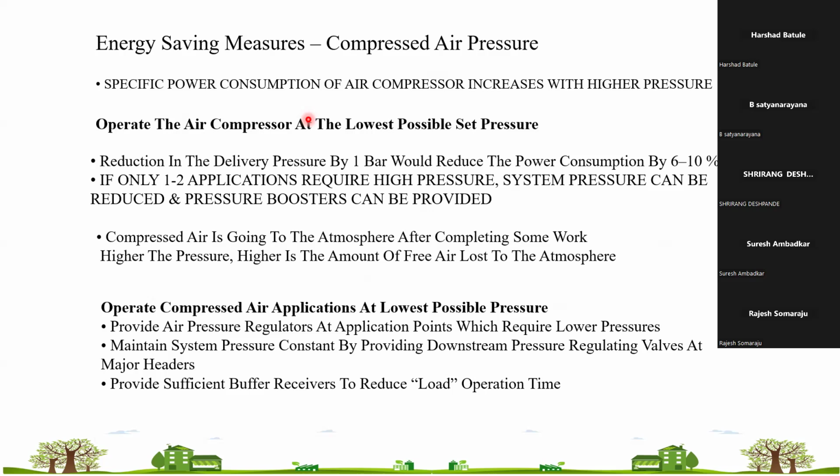Whenever I do an audit or we see on the field, there are multiple industries where people complain that they don't get pressure at this length. We do have a 500-meter circuit, but we don't get pressure. So we have installed another compressor, or that particular user has a different compressor. Such kinds of energy wastage are there in industry.